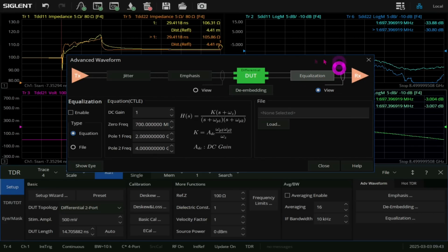On the other side, equalization is done typically by the receiver, and this is, in this case, supported by a CTLE, a continuous time linear equalizer, and you can apply some function to compensate for the losses of the channel, boost some of the high frequency content. In advanced wireline systems, all of these are used in combination, and there are advantages and disadvantages to pre-emphasis and equalization. So in this case, we can take advantage of the equalization.